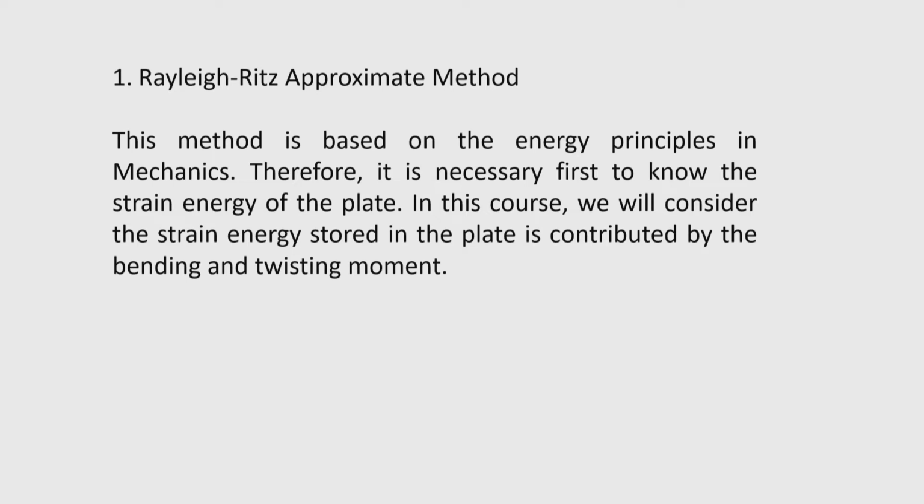In this course, we will consider the strain energy stored in the plate is mainly contributed by the bending and twisting moment. That means, the contribution of in plane forces and contribution of shear forces towards the bending strain energy are neglected. So, that is a very important thing, only strain energy due to bending moment and twisting moment has to be considered in the formulation of the problem in this course.